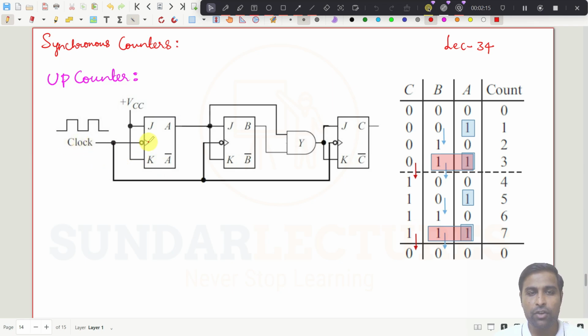See, if you give a clock pulse, this clock pulse is given to this flip-flop, as well as the same clock pulse is given to another flip-flop. That same clock pulse is given to all the flip-flops. That is the synchronous sequential circuit. Try to understand. If you give one pulse, then it will be applied to all the flip-flops simultaneously. That is a synchronous sequential circuit. And if you go for an asynchronous sequential circuit, these clocks are not simultaneous for all the flip-flops at a particular instant of time. That is the only difference. Anyhow, we will see that after.